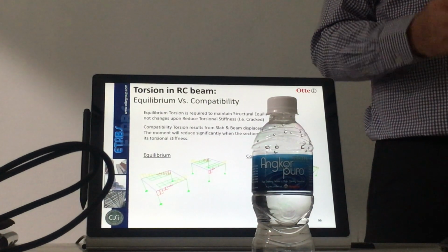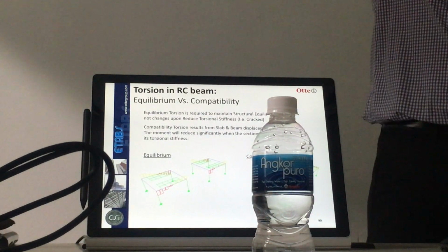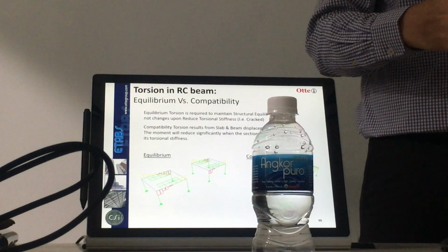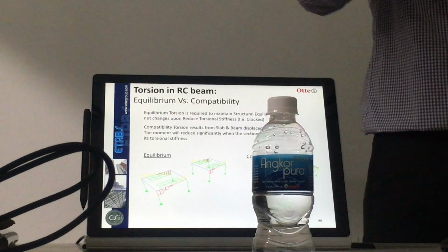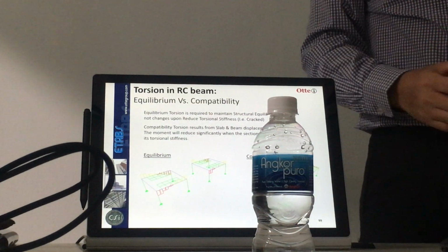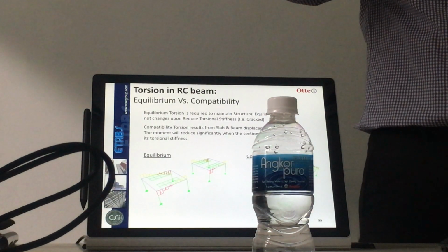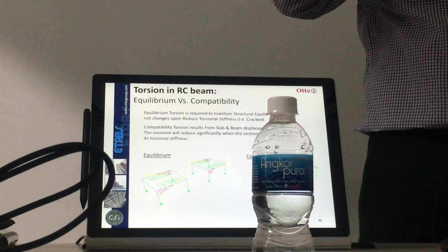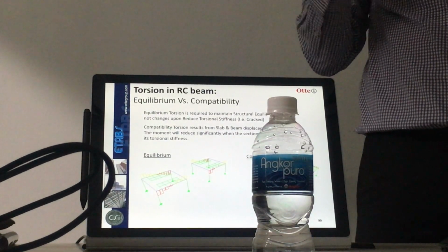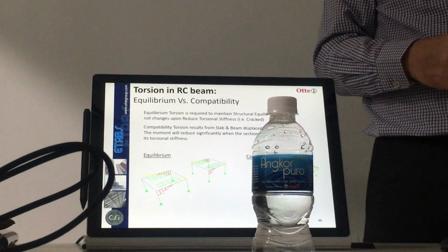Because why? In a building, look at the beam. Beam have no axial load, only bending. So it will crack accordingly. But column will crack less. Why? Because even though it has bending, it has compression load from the gravity load coming down. So it cracks less. So the reduction in stiffness is only 30%, becoming 0.7. The beam is 0.35, it reduced by 65%. So now when I adjust the stiffness accordingly, my load distribution will be more realistic. That's what we use the crack section property for.